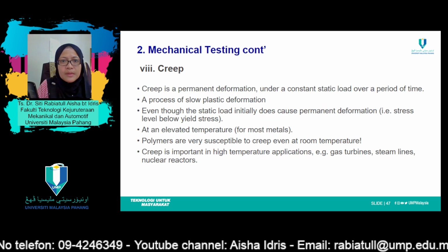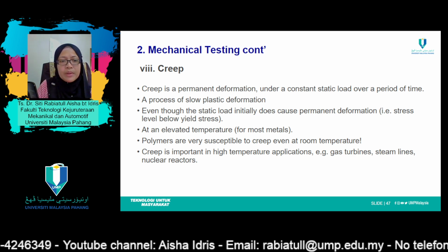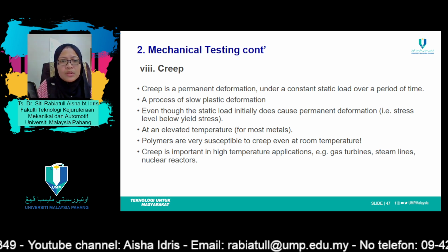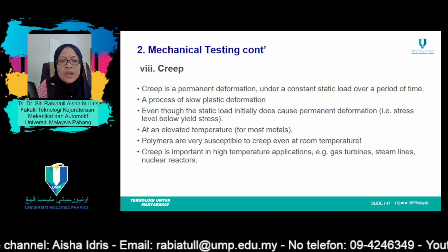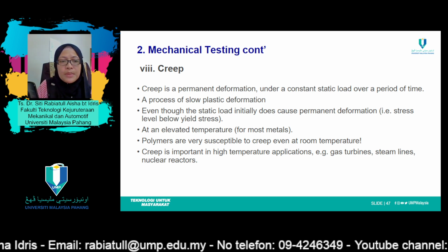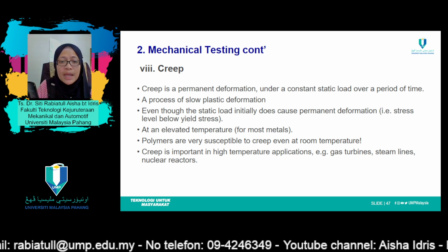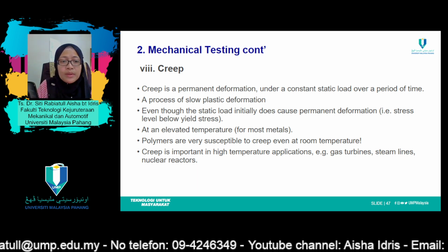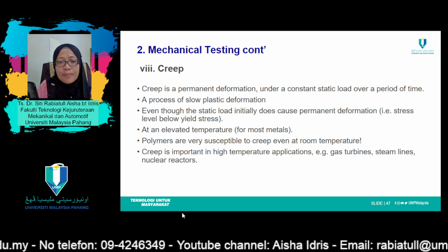Okay, the last testing in this topic is creep. Creep, sometimes referred to as the stress relaxation test, is used to determine the amount of deformation a material experiences over time while under a continuous tensile or compressive load at a constant temperature.